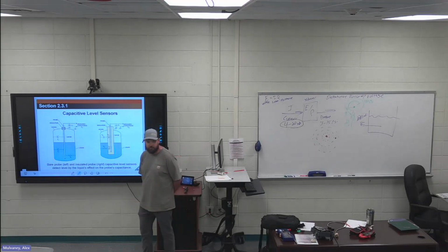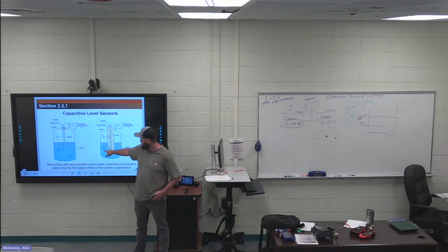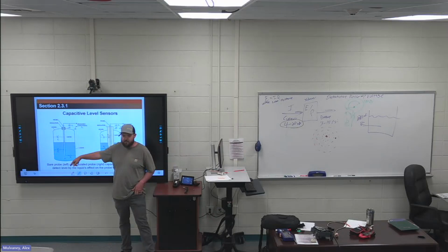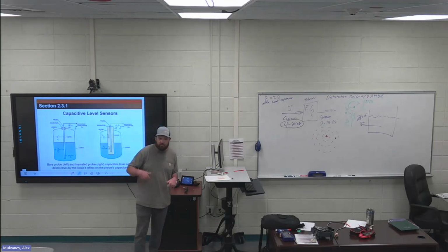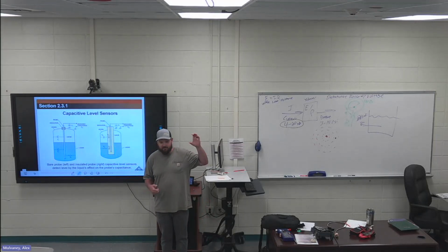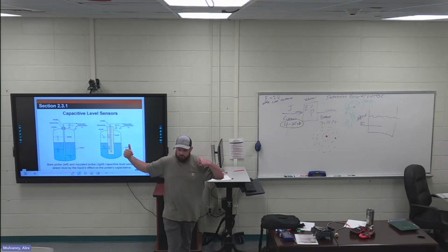Michael, this is probably what you were talking about. Like you had to know the temperature of the tank. That's what this resistor is down here. That's our RTD that's measuring the temperature of the tank. And based on that temperature, it can put a fudge factor in the controller. The controller can see I have this capacitance with this temperature, and then output us the exact level.